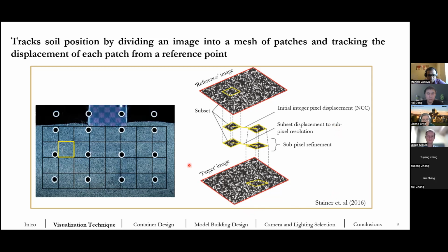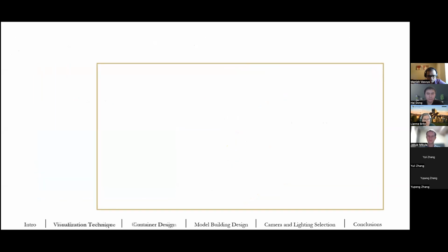So this new software also provides an improvement of a factor of 10 for all different deformation modes. Then the last step in this kind of analysis is the displacements are converted from pixel space to millimeters by calibrating these displacement vectors that we get against a grid of control markers that we know the location of.